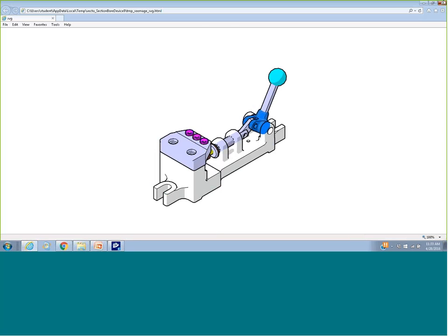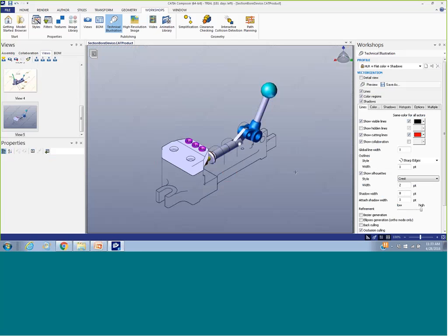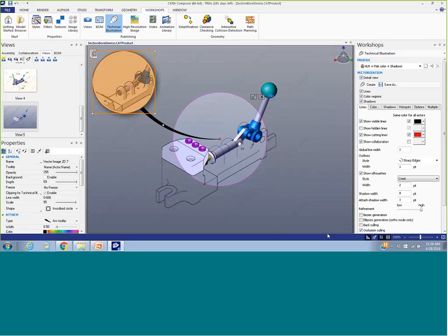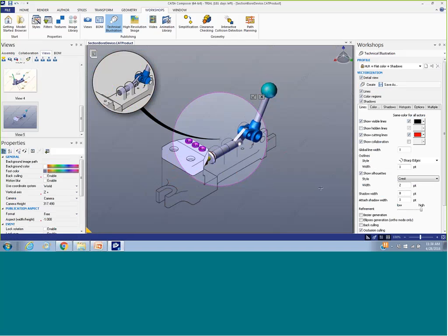So you can quickly create images with either of these here. And then also, again, you can still make a detail view here. So again, I want to make a detail view of an area. Again, move this wherever you want it to go. Once you've got that circle around where you want it, you've got to move the handle in the corner to do it. But you can then come over and say detail view again, create. It would now create a detail view of that area within this model. So that's basically what you would do to export if you wanted a static 2D image.